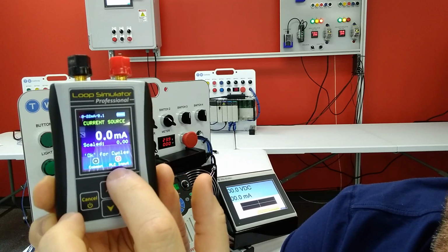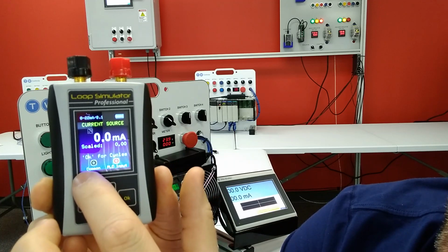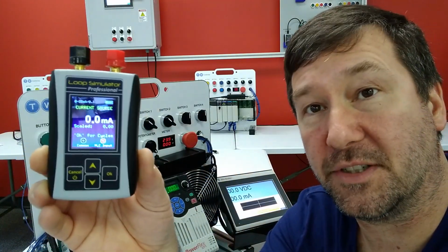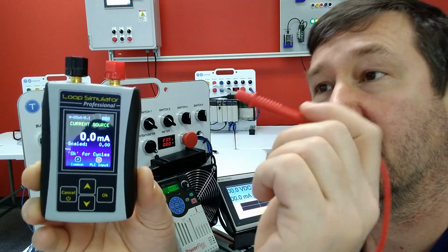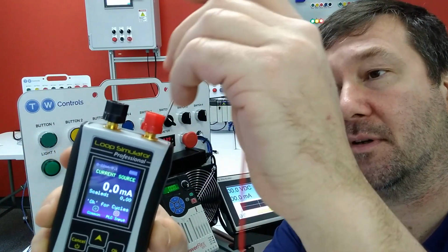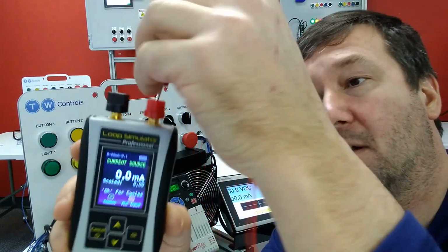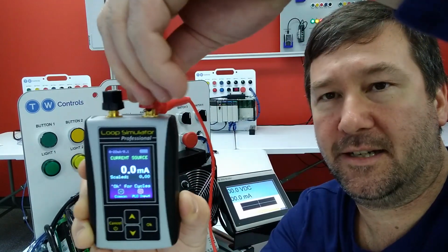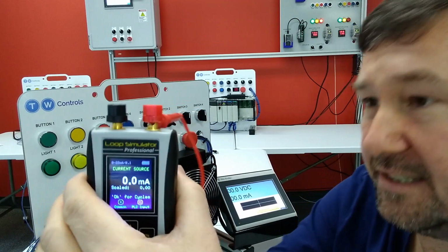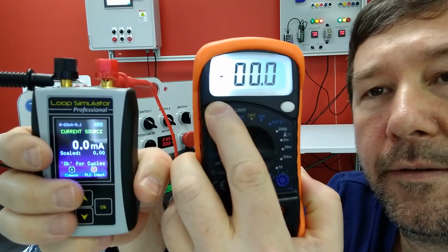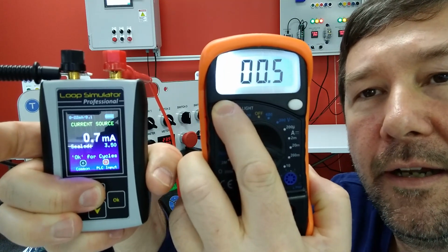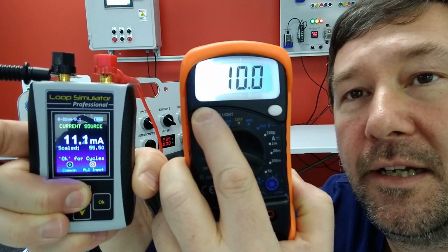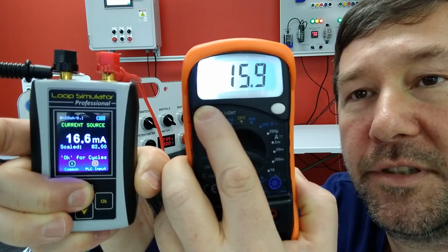And then at the bottom of it, it says PLC input should be the red post and our common should be the black post. In this case, our PLC input will be our voltage input from our multimeter. So the red lead will go to the red post. Also, you can simply stick them in the top, or if you unscrew these posts, then you'll find that you can slide a wire through it and you can tighten it down. That way it'll stay in place. Now we can use the up arrow and drive our milliamp signal up, and we'll see the same signal on our meter. And we can bring it all the way up to 20 milliamp.